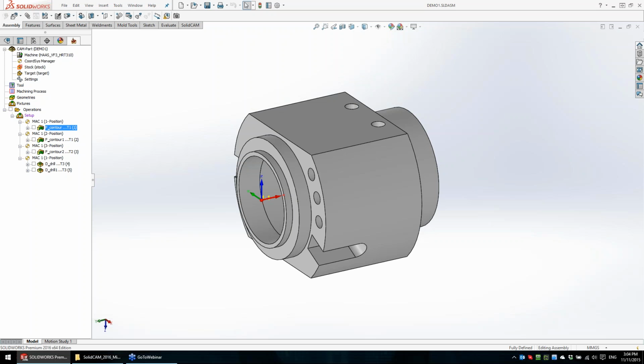It was a very difficult step in the previous versions, because if the kinematic is different, you need to edit and recreate the coordinate system, and some geometries you need to define again. Levels, all the operations, you should be involved in almost every operation to fix the part to work on another machine. So I will show you today another way to move the part from one machine to another, which is simpler in 2016.